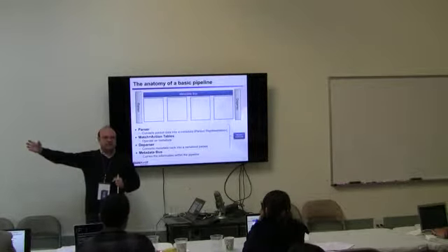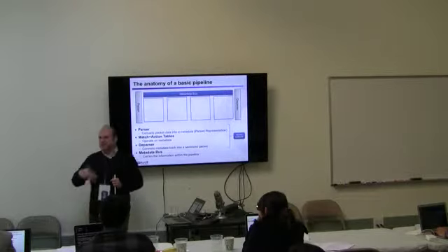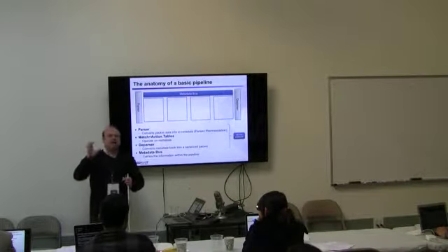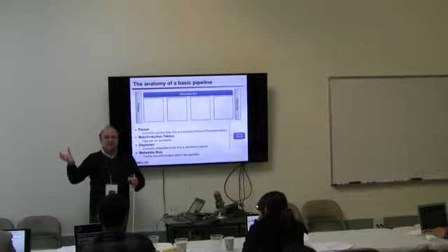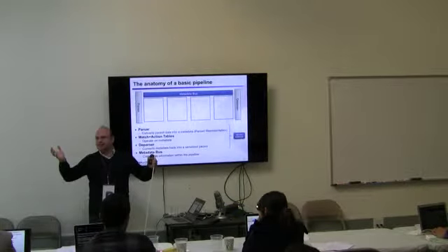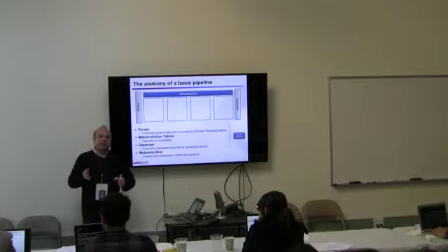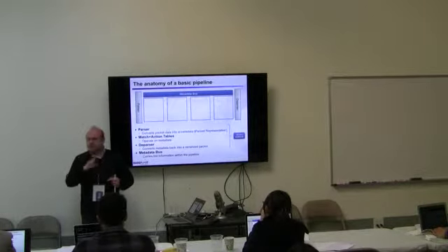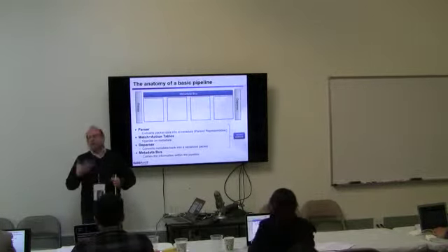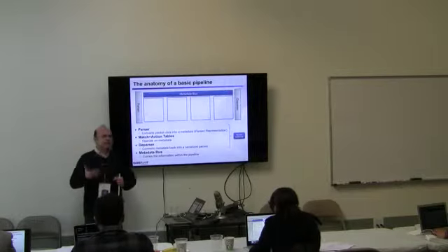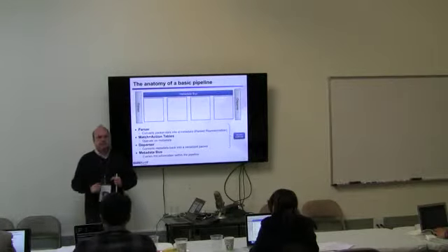The CRC. Right, it's not quite a checksum, right? Because we use the polynomial. And if that CRC is wrong, that's it. We just have to drop the packet where we were. Usually that means that some of the counters might be a little bit off, but that's the price people pay to have very low latency.